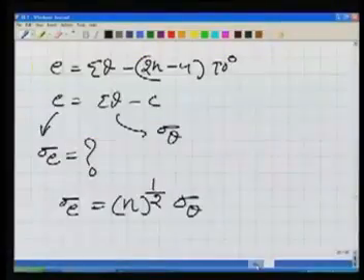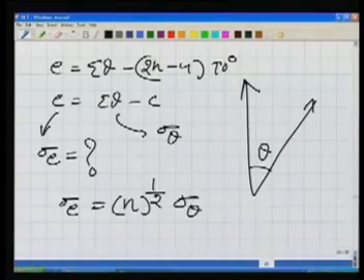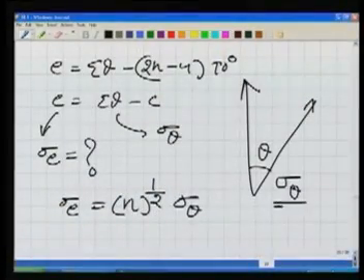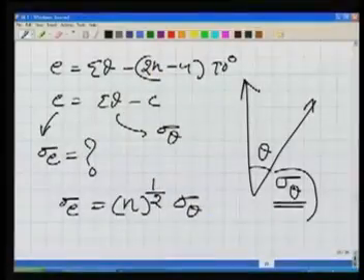There is a procedure for that. When we are measuring an angle theta, there are some errors which get introduced. This is because of bisection, and because of reading. We have seen that if you are measuring by repetition or reiteration, what will be the error in measuring any angle, and how to determine it. So we know, for the theodolite which we are using in the field, and for a person working in the field, what this value is in measuring one single angle.